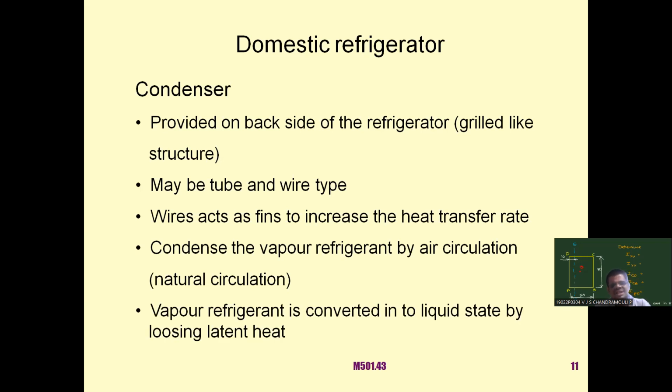And the vapor refrigerant is converted into liquid state by losing its latent heat. So the vapor refrigerant which is entering the condenser will lose its heat, only latent heat, so that the refrigerant which is entering the condenser is initially dry and saturated, and after the condenser, it is dry saturated liquid.